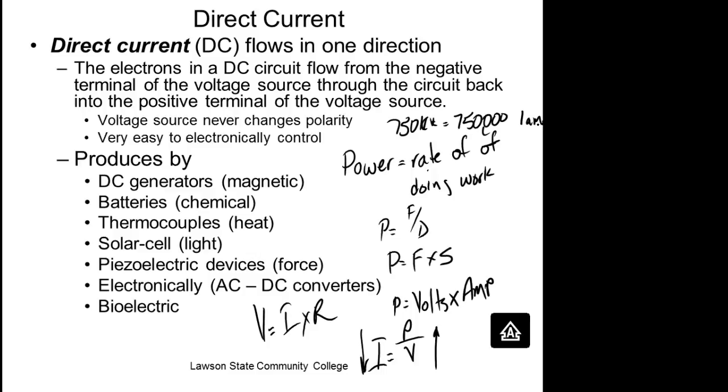So what they do is step the voltage up for transmission. That way, instead of using copper, one of the best known conductors, they can use aluminum, because the voltage is so high. Even though aluminum has a good deal of opposition, if we make the voltage high enough, we don't get very much line loss, which is how much loss you get in the conductors themselves.